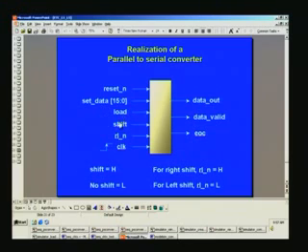Thereafter you can give a shift control, and this shift can be either left shift or right shift, this being 1 for right, and it's being reckoned at positive edge of the clock, and you have an output corresponding to the serial stream, bit stream as such, right at data out, and when it is valid will be indicated by this data valid signal, and once all the 16 bits are sent out serially over this, an end of conversion will be generated.